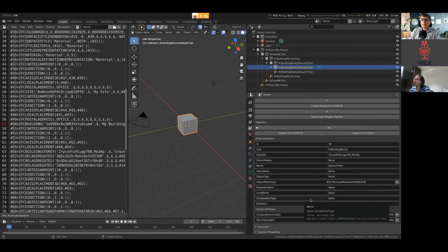What I do want to highlight is that the BlenderBIM add-on takes it very seriously not to try to add decoration around IFC data. And this is something that's extremely different from other BIM applications. For other BIM applications, most of how IFC works is hidden from you. And as a result, even if you don't mean to, you can accidentally produce quite low quality IFCs simply because the default position is to hope that the application is exporting or importing or analyzing it correctly.